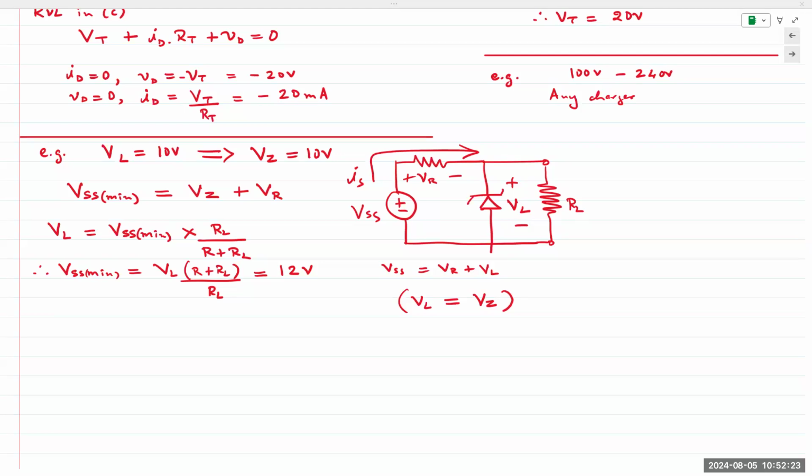For nonlinear elements like diodes and transistors and FETs, the methods are numerical, meaning we don't always know the answer. We have to create a lot of models, and there's an iterative process where we would try an equation, obtain an answer, see if that answer matches up with what we require.